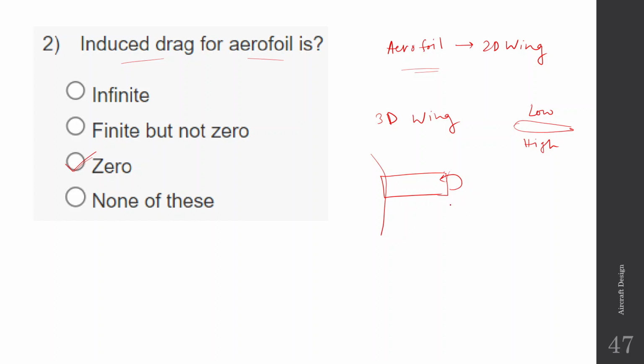So at the edge of the wing we have these kinds of vortices, because the high pressure air flows from below and comes up. Towards the edge of the wing, the lift is lesser because of these motions of the air. But in the middle the air flow is like the aerofoil only, so the middle part produces lift, but towards the edge it decreases.